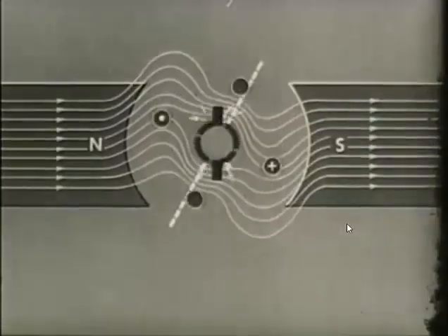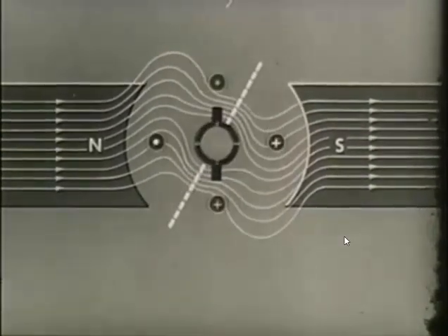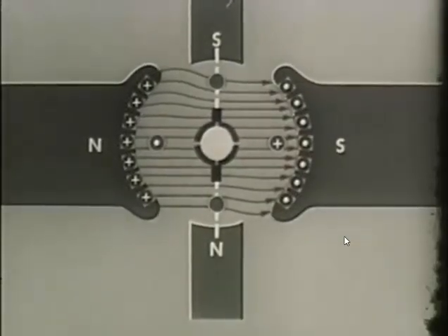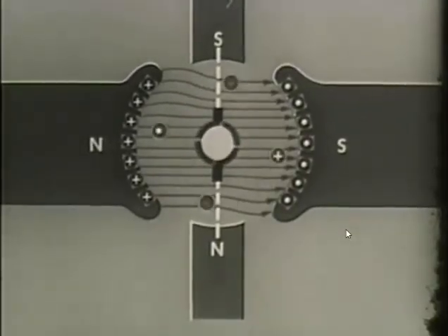The other way of maintaining the neutral plane is by adding interpoles to the generator field. Cara lain, ditambahkan interpole lagi di antara magnet utama. These interpoles are small magnets placed between the poles of the main field magnets. The interpole magnet fields oppose the fields created by armature reaction. The neutral plane is moved back toward the correct position. Maka neutral plane-nya akan kembali ke posisi semula.